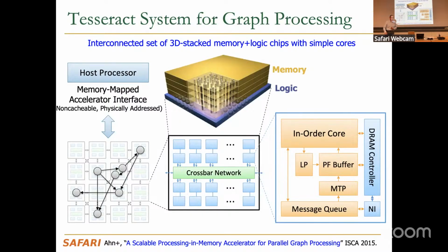Well, interposers, you can do that, but still it's a different interconnect, right? It's not true 3D stacking. With true 3D stacking, you can do it. The problem is what kind of logic can you put over there, right? Modern HBMs, at least so far, fabricate the logic using a DRAM process. As a result, your logic sucks. Meaning in terms of the size of the logic, it's huge. You cannot clock it very high. And also, leakage is bad.